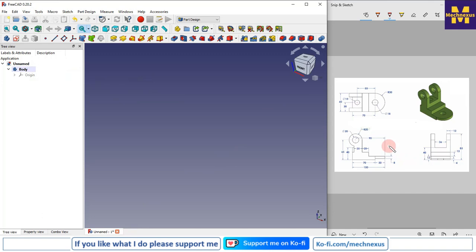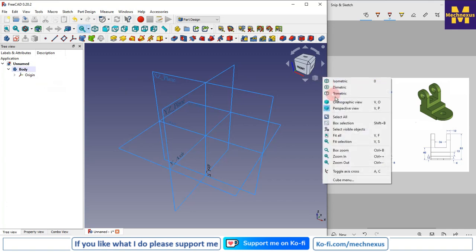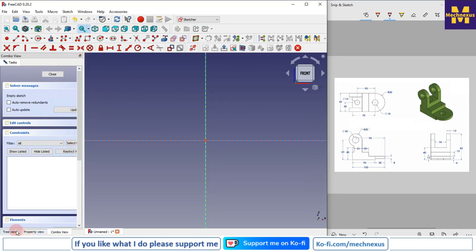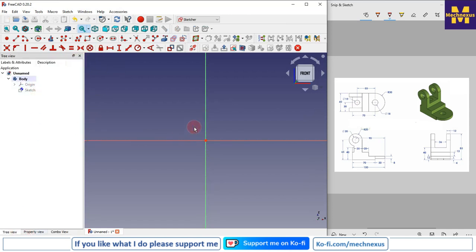So first we will read our drawing. As we can see, here is a material removal and here is a material removal. So for this type of part, first we will make a solid block and then we will do the material removal process. So I will select the XZ plane and create a sketch, and I will turn off my origin plane.